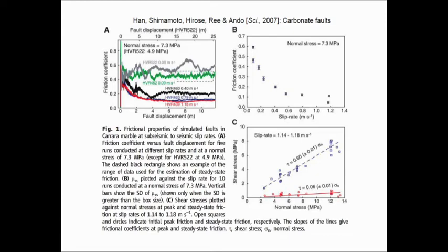So here are friction coefficients dependent on the slip rate of the test. Those are different for the different curves here. At a fixed normal stress, not as large as we would like, but healthy. And what you see is that as the slip rate goes up, the friction coefficient goes way down in the range where we activate this thermal decomposition.